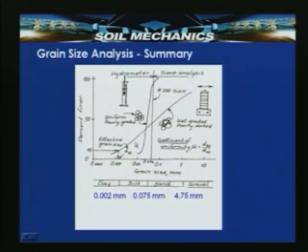For particles finer than 75 micron, it is required to use hydrometer analysis. Depending upon their sizes, the particles settle, and the hydrometer reading has to be worked out with different corrections to get the fine particle size percentages. Once corrected, it can be joined with the original grain size distribution curve to get the complete curve. This hydrometer analysis is required if the percentage of fines is more than 12% or so.